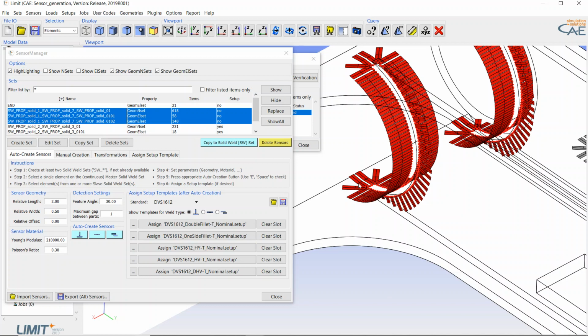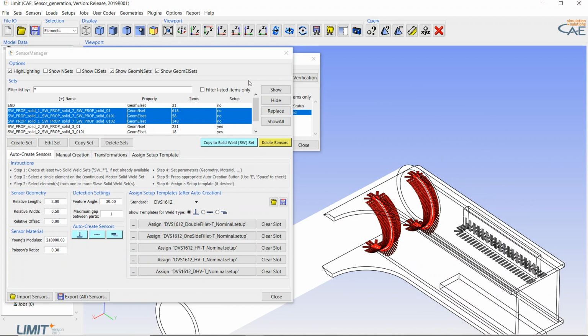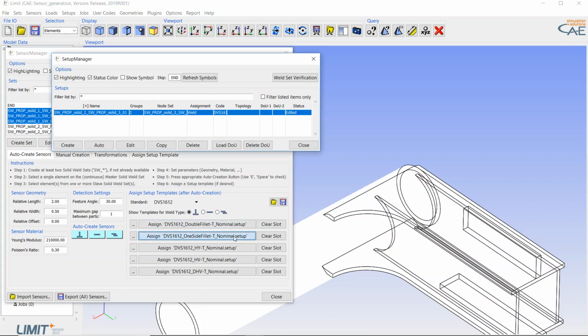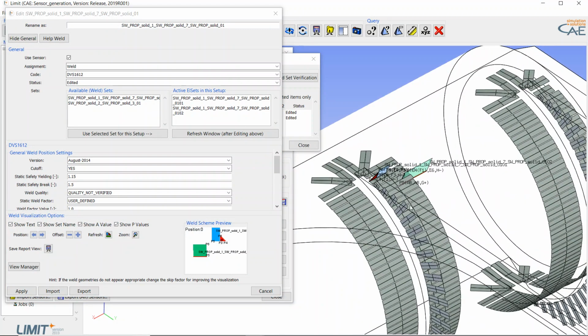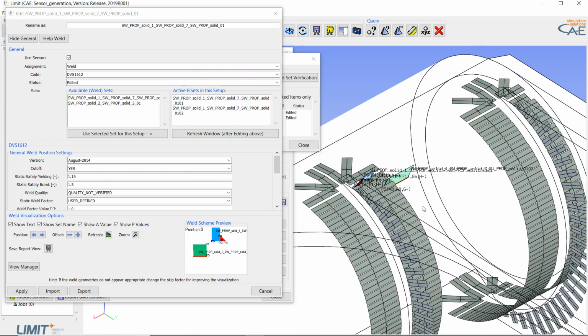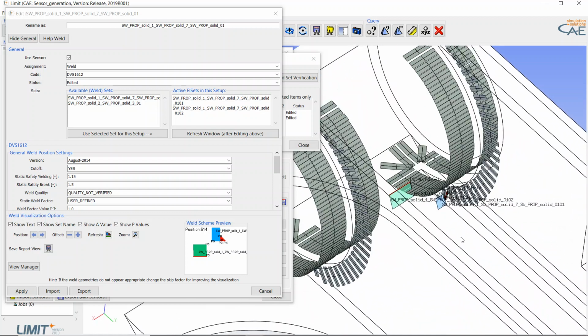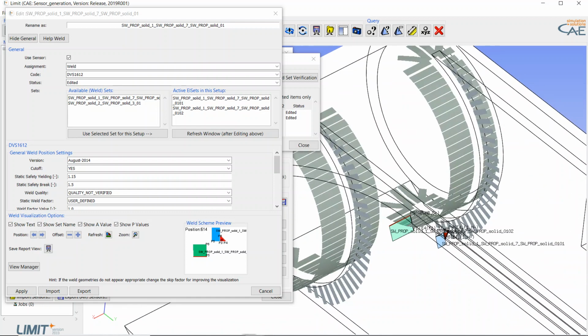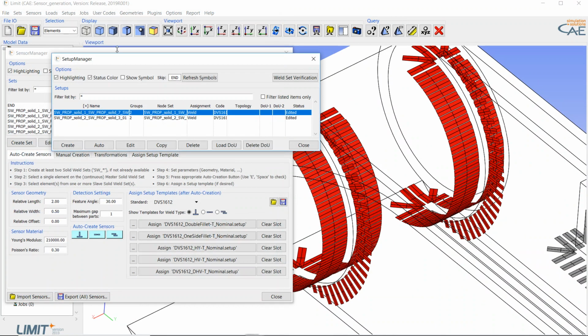Nice position covering the 45-degree corner point. Okay, and we want to use a one-sided fillet weld in this case, and then simply hit the button with the weld you would like to use, and then we can sweep through the positions to make sure that both sides have the right orientation of the weld symbol. It looks okay on this side as well, and with apply I can finish this operation.